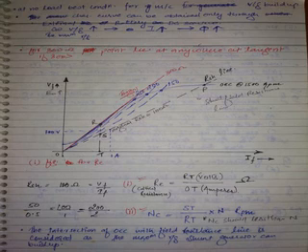Now, for this machine, you will be given the critical resistance at a given speed. For example, if the machine is running at 900, it will excite. Above 900, it will excite. Below 900, it won't excite. Means there is only one value of critical speed for a given generator. Yes or no? It is 900, only that. If you operate the machine above 900, it will operate. Below 900, it won't excite. That is the meaning, only one value. Like that, you don't have one critical resistance value. Critical resistance depends on the operating speed of the generator.